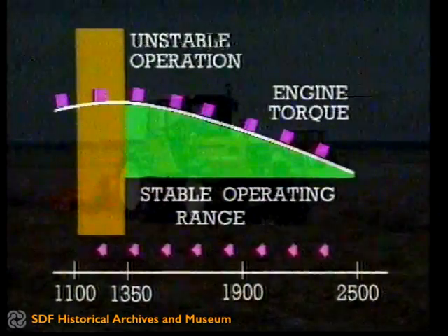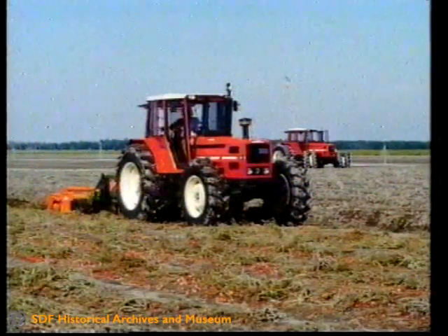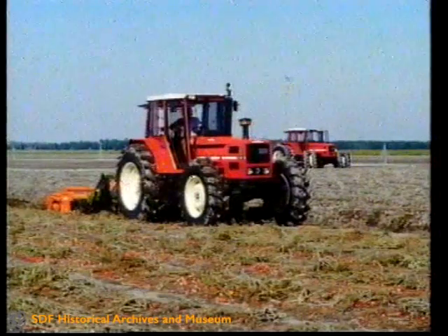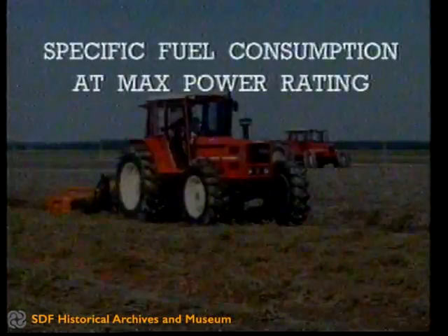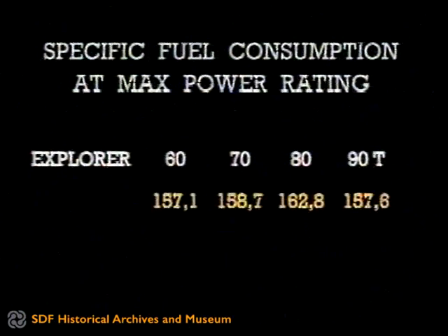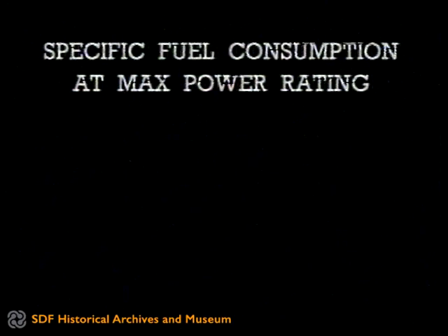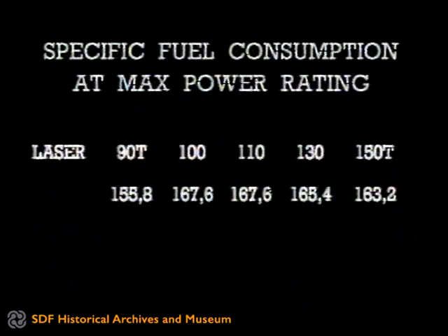High drive torques, capacity to surmount even the heaviest loads, extremely low specific consumption figures, all below 168 grams per horsepower hour, with peaks below 160 grams. These figures are confirmed by official ratification tests to DIN 70020 and are absolutely the lowest in the field of tractor production in the world.